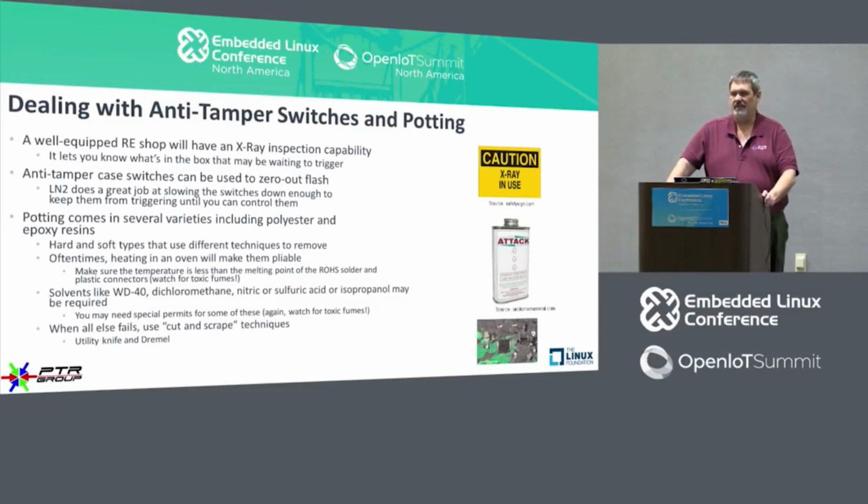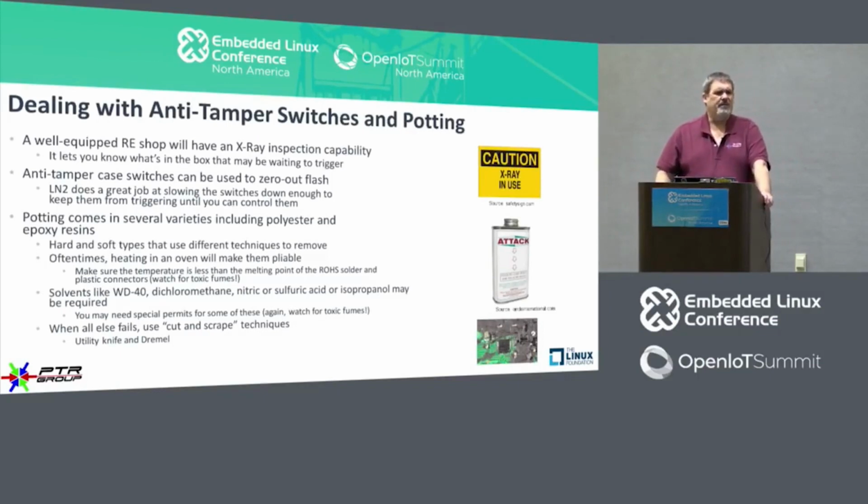Now, dealing specifically with anti-tamper switches and potting, any well-equipped reverse engineering shop will have an X-ray inspection capability. So it's an X-ray machine, and basically you just simply put the device under the X-ray and take a look at it, see what it looks like in the X-ray world. That will typically let you know that there may in fact be some tamper switches inside of it.